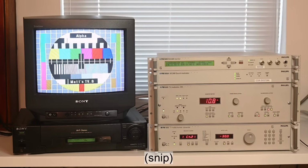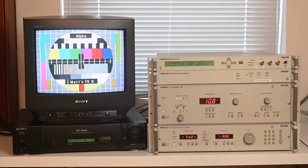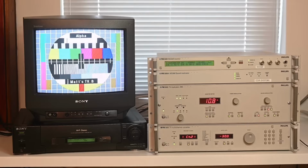Okay, so our NICAM is switched on, and at the moment it sounds exactly the same as it did before. Let's try some switching. So yeah, it sounds awful. The video is still absolutely fine, but if we look down at the VCR, the NICAM stereo indicator on the LCD is flashing off and on. We've got this message on the screen, and also if you look at the NICAM monitor above the transmitter, the alarm LED is flashing, and this is indicating that something is wrong. Anyway, let's switch off this noise so we can talk a bit about what's going on here.